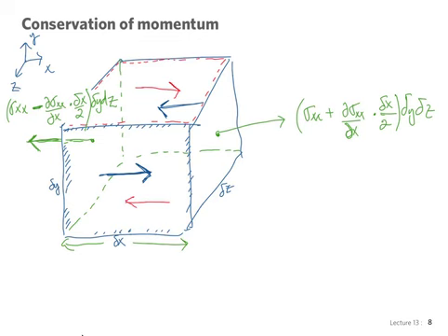Okay, so the same applies to the blue and the red ones. The red here on top is a tangential stress on the top wall, and what is the outward normal of that wall? What coordinate direction is it? Y. So the first subscript is y. What direction is the stress pointing? X. The second subscript is x. Good?